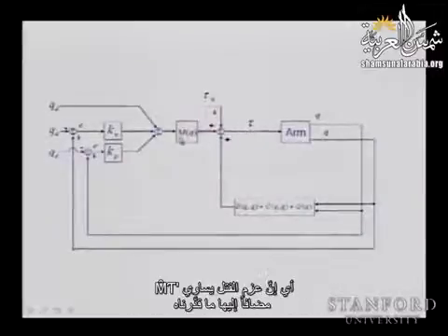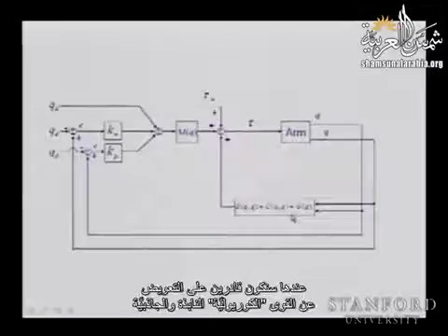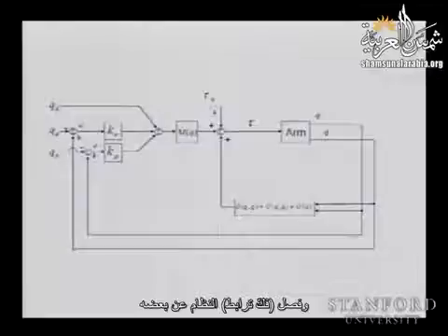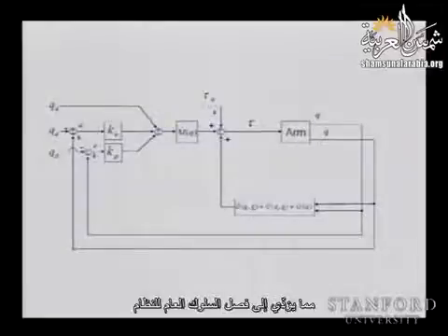So the torque is m hat times torque prime plus those estimates. And then we are able to compensate for centrifugal Coriolis gravity forces and scale our gains and decouple the system. And the overall behavior of the system will be decoupled.